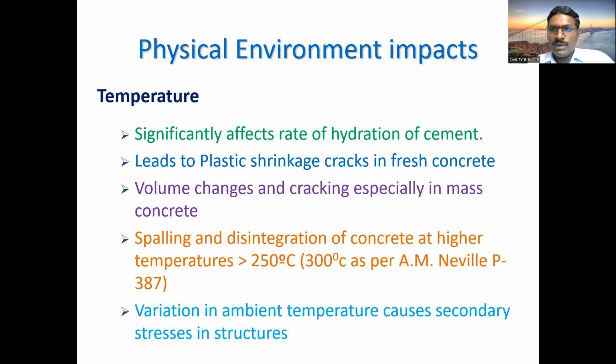The very important part is the rate of hydration. In the curing process after placing, from the next day onwards after the setting time, we give additional water as curing. If the temperature is more, the rate of hydration will decrease for whatever water we are providing for curing. Then this leads to plastic shrinkage cracks, then volume change and cracking, especially in mass concrete.